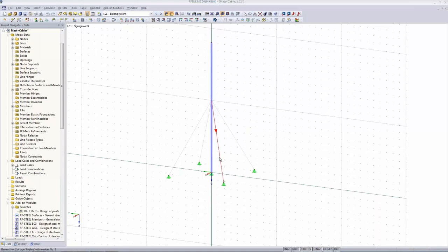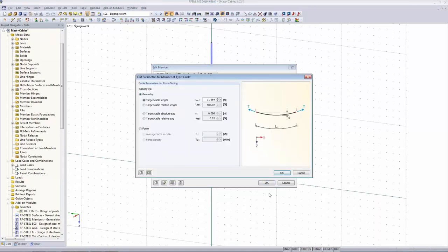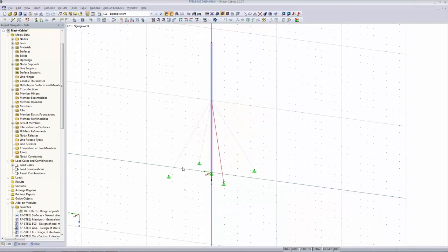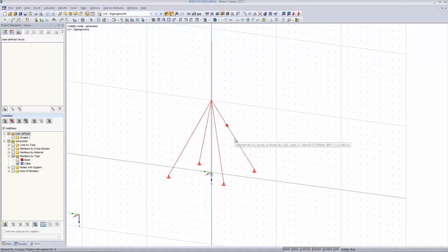And I show you what I did. This is a defined cable, and I think I have to select them all. So I go to fuse, and these visibilities are quite nice, really try to use them as much as you can. Now everything is hidden, just grayed out, and when I select, I only select the cables as I've chosen here. So this is the only thing available now for selection.